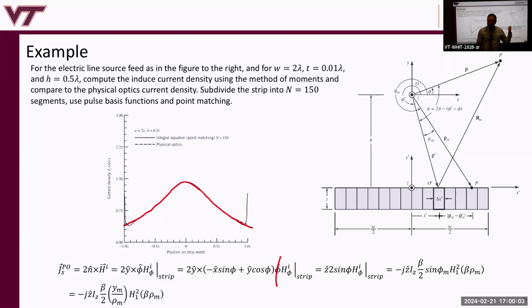Remember we did scattering at the end of last semester? We could only solve problems that had spherical symmetry, cylindrical symmetry, or planar symmetry. We did scattering from plates that had finite width or infinite length. We did scattering from cylinders, dielectric-coated cylinders, or we did scattering from PEC spheres because we needed to use the wave functions, which were specialized for those coordinate systems, right?